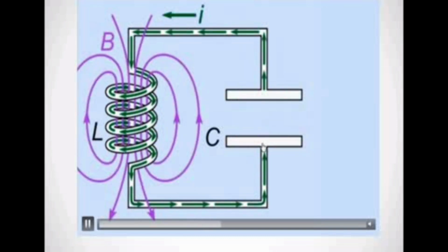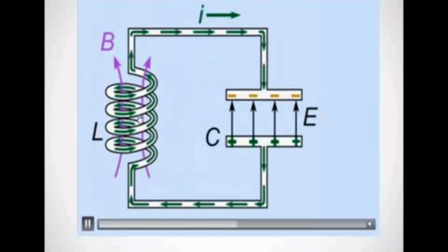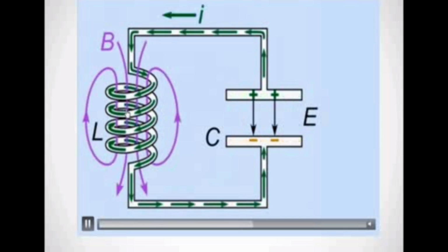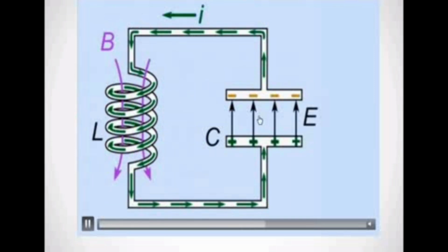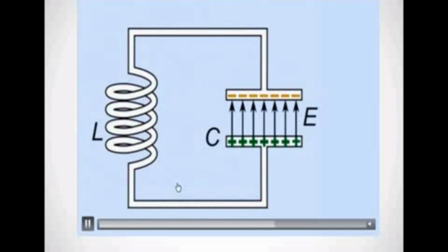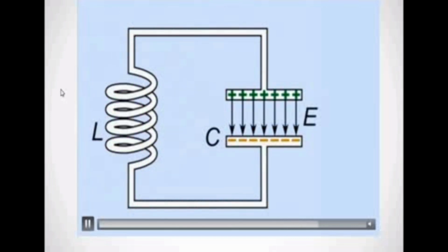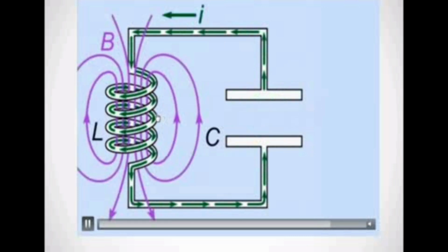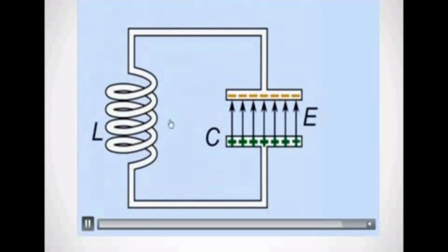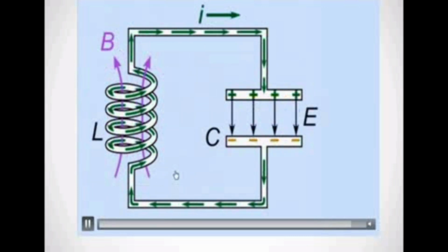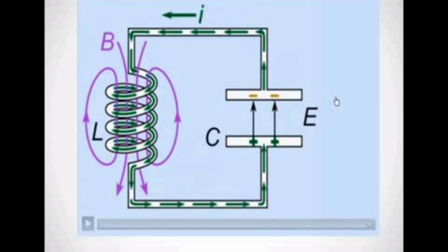So the capacitor energy produces a magnetic field in the inductance. That magnetic field is again stored in the form of charges in the capacitor. So it occurs continuously and alternately. Once we give the energy, it continuously produces electromagnetic energy and capacitor energy like this. So this is called a tank circuit.